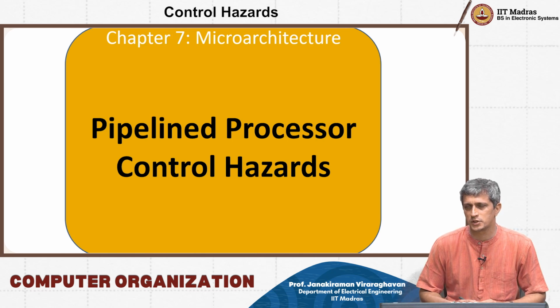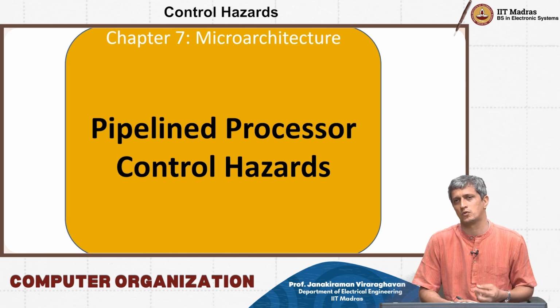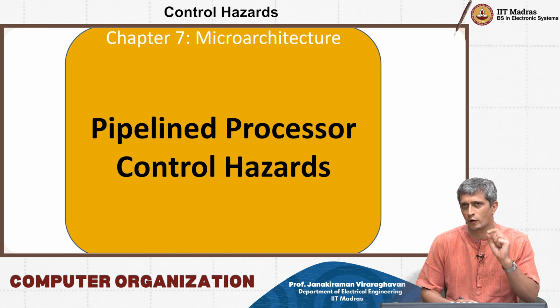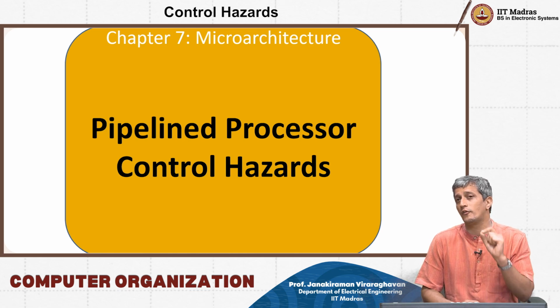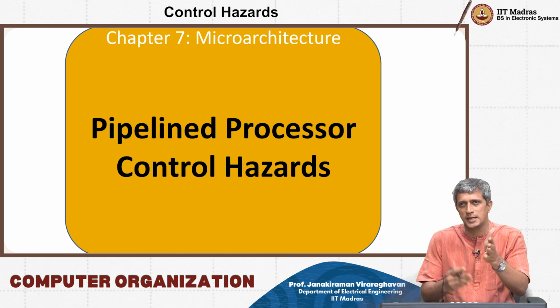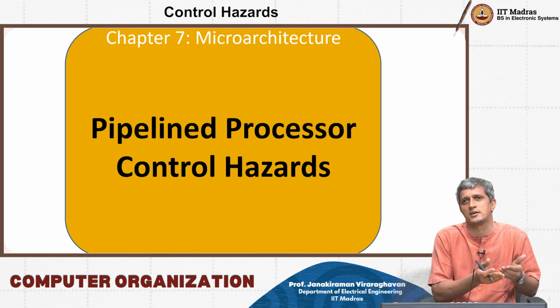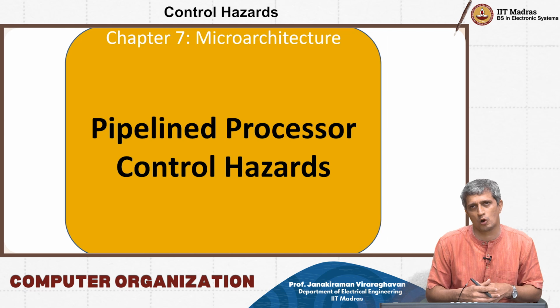So in the last couple of lectures we looked at pipeline hazards, specifically data hazards, and we solved the problem using two techniques. One is employing the clock bar, the inverted version of the clock, for the register file to handle the read immediately after write problem. And then we also looked at the idea of register forwarding, where the data is anyway captured by one of the flip-flops in the pipeline and you don't have to wait for the register to actually get written back before you give that result to the next operation. So therefore it's a bypass path, or register forwarding as we call it, right?